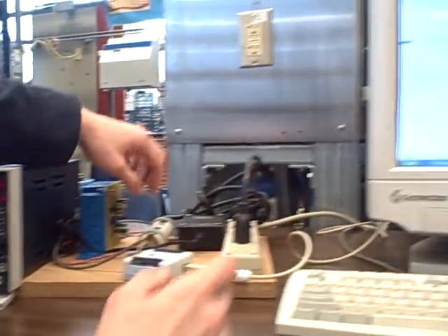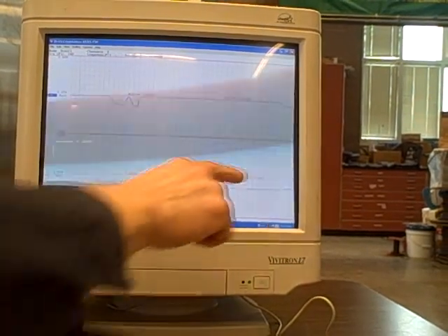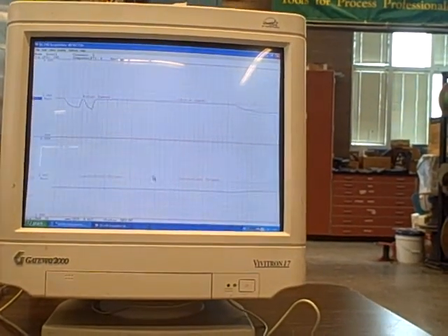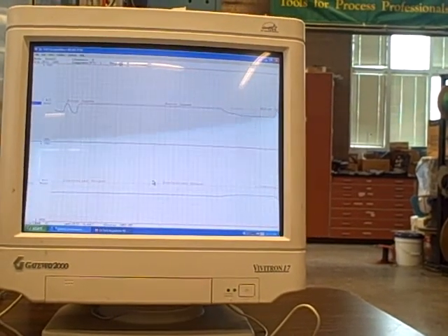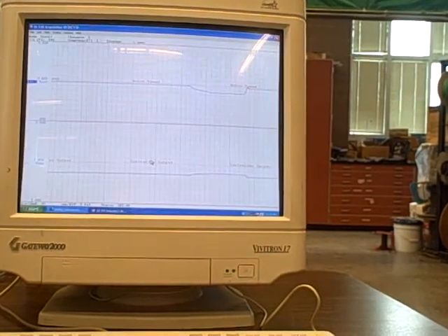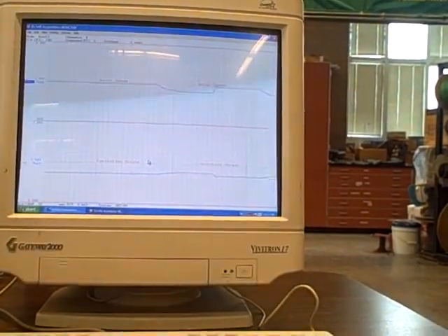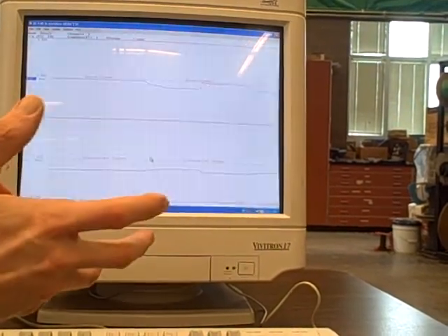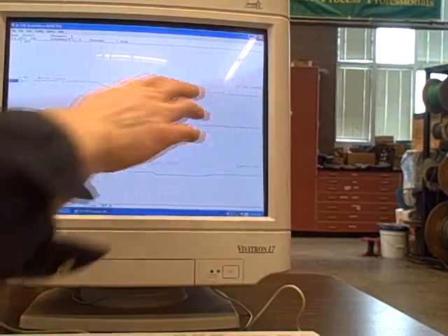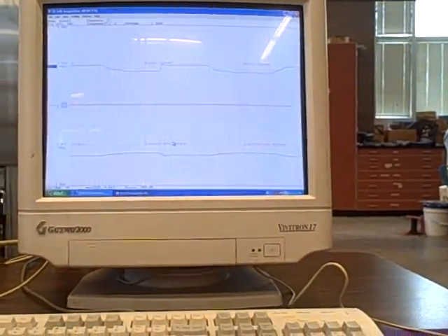And then going back to the screen, if I slow the motor down, I see the output rise. It's a little easier to slow it down because it's not as aggressive control action as we had before. However, when I let go of it, we don't see the oscillations we did before because it's not overreacting. So I've killed my oscillations, which is a good thing, but the price I pay for that is having a controller that doesn't correct quite as aggressively as I'd like it to when it sees a change in load. So here's what I have to do.